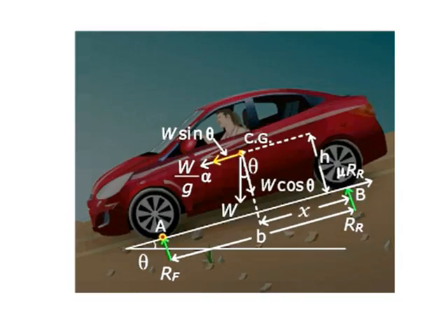Suppose this is a vehicle, a car which is moving down on a hill. You can see the road gradient, which I'm assuming is theta, and the vehicle is moving downwards. If the vehicle is moving downwards and suddenly a brake is applied, or if the vehicle is accelerated by a retardation or acceleration value of alpha, there will be these many forces acting on the vehicle. This is a free body diagram of a vehicle moving down on a hill, and suppose the brake is applied, so a retardation of alpha is achieved on the vehicle.